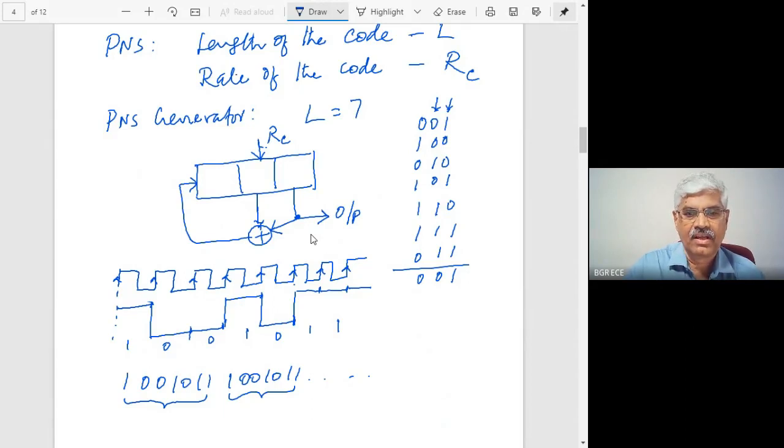So we needed a noise-like sequence. But if you have to generate such a sequence, it is not really noise, it is a deterministic sequence, which can be generated using a shift register like this, about which we know completely. Still, we would like to call it a random sequence because it has all the properties of a noisy sequence. Suppose you had a long random sequence which is not repeating, it will have certain properties.